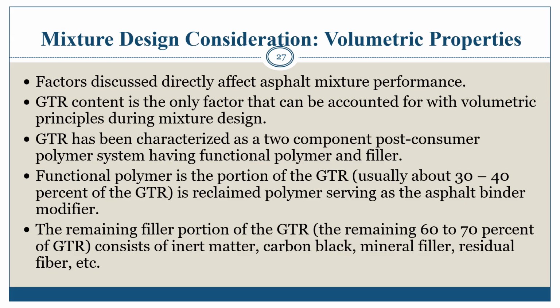This should be given consideration when designing asphalt mixtures containing GTR or GTR modified binder. A common practice with some state DOTs has become to increase the asphalt design binder content by 0.2 to 0.3% to address lean mixture concerns and early age cracking of GTR modified systems.